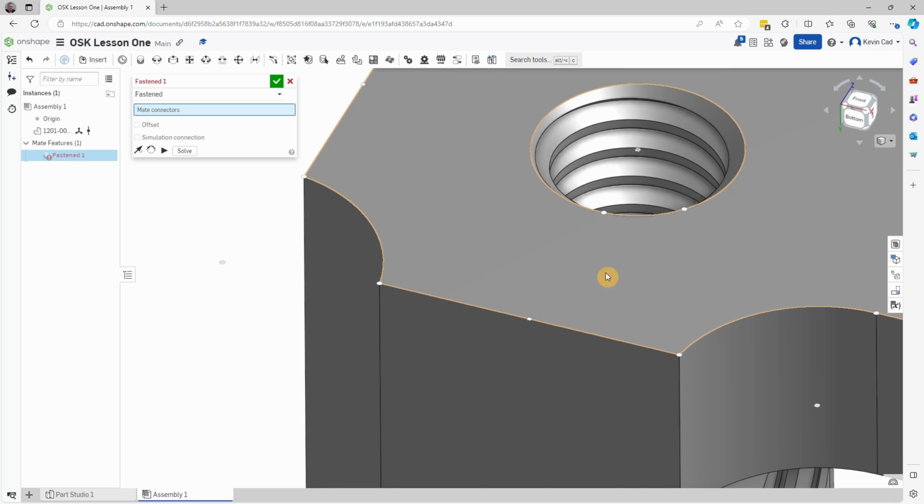So this is the face here that I'm hovering over. And as I get close to that, it's giving me z-axis perpendicular to that. Now, I've let up on the shift key. Now I'm gonna come over to this line and I can actually select a line. Now check out what happened to the z-axis. The z-axis is now aligned with this line segment.